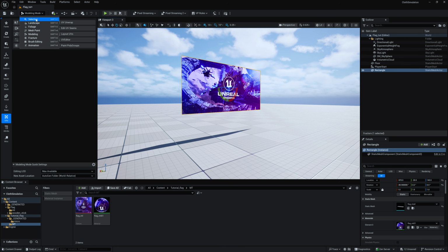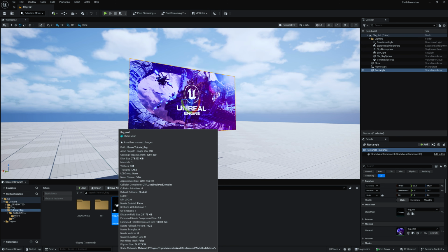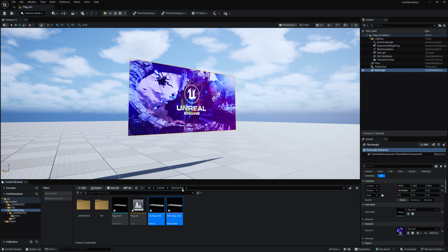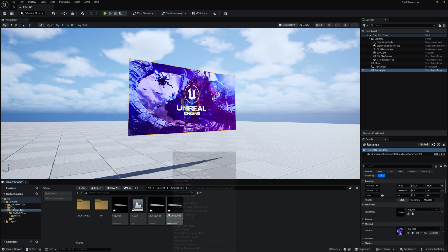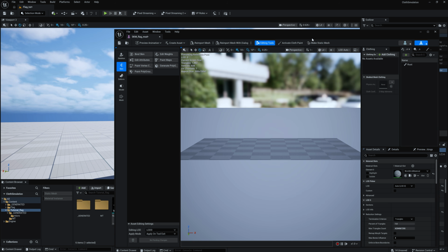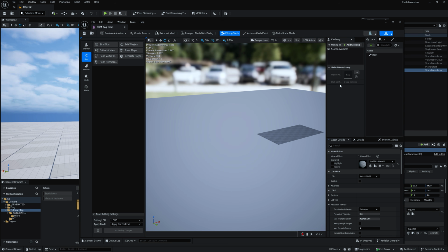Now get back from this modeling mode to the selection mode. Now select this model, right click and convert to skeletal mesh, and after that press convert. Now it will create this entire flag into a skeletal mesh. Now you can find this purple or pink color light kind of a thing, so simply double click this, so it will open in a new window. Now what you need to do, select the root and you can move this to something like top, and now